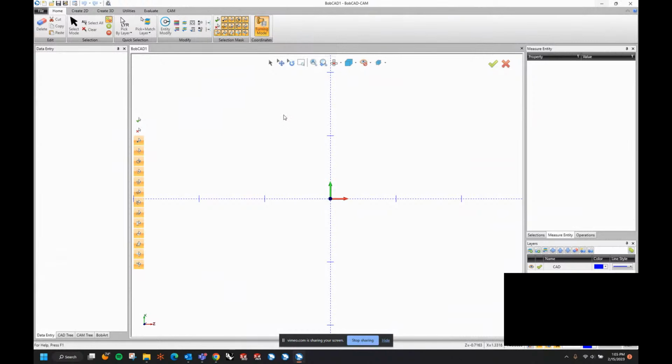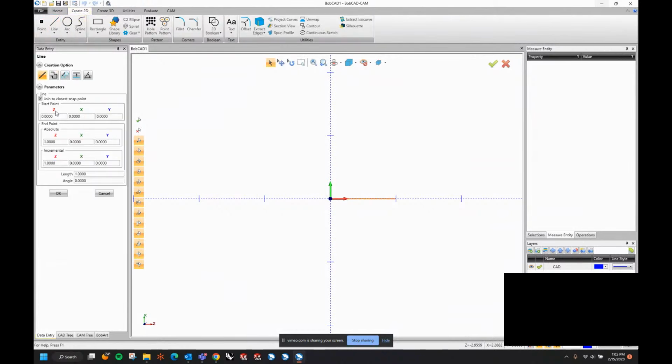Well, when you turn on turning mode, it replaces your X, Y, and Z axes. Instead of being on an XY plane, it goes to an XZ plane. Actually, I shouldn't say rotates. It just renames those CAD functions. If I go to a create 2D function and go to line, it now says ZXY. If I turn off turning mode, it's now XYZ.